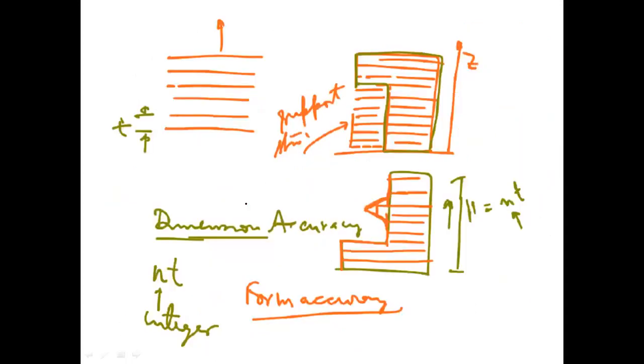So as I said, in almost all the cases, you have to be very careful with respect to orientation. Now, as I explained this example, you might have understood by now. If this is my part, the green is my part, and that has been layered, you have to decide whether this overhang is so significant that the object will topple out. A layer thickness has been defined.